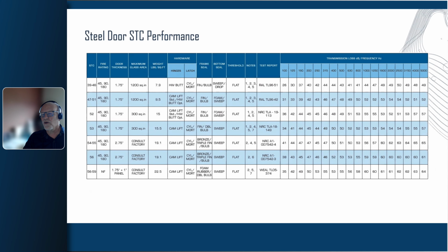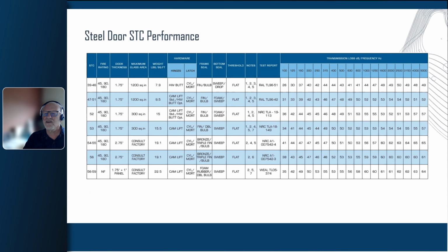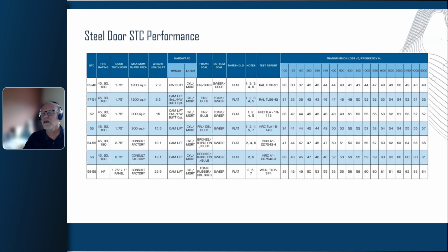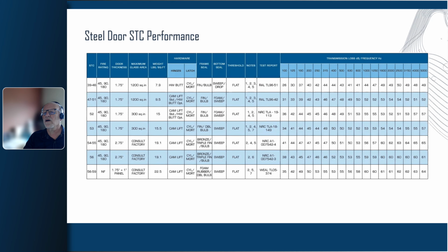And I don't want to go through it with you on a line by line basis, but I want to show you maybe just one line here in this range. And I consider this the mid range, the STC 47 to 51, and talks about what's achievable. This is with Ambico. Different manufacturers are going to have different requirements. So some are not going to be able to get 1 3/4. Some of them are not going to have fire ratings, but this is widely what's available.